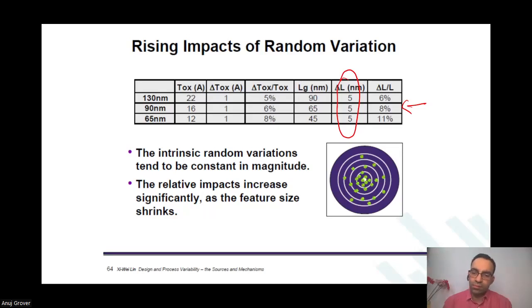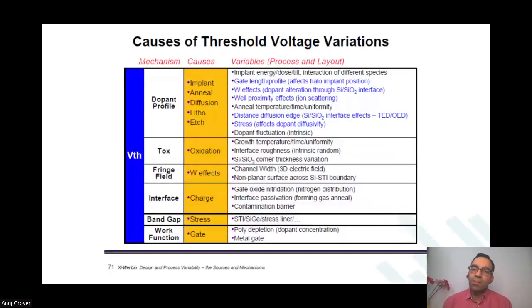And in the random variations, there was also one subcategory of pseudo. How is pseudo different from that? Pseudo is something like you have two devices, but there is a temperature gradient because of some heat being generated in some place. Physically, the devices were similar, but now due to higher temperature in one device and lower in the other, the mobility has changed a bit.